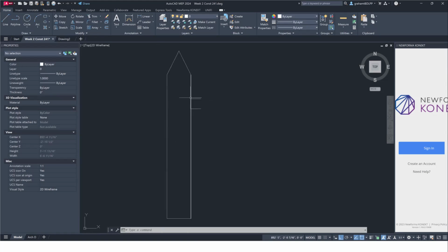So it's 6 inches down from the top, then the first line, and then we got 2.5 to this. Just copy it with a base point, give it a direction, and then tell it 2.5 inches. First line is 6 inches down, and then the second line 2.5 below that. And the line length is 2.5 inches long. Okay, it doesn't necessarily matter if these are perfect, but you'll see what's going on when we get to the next step.